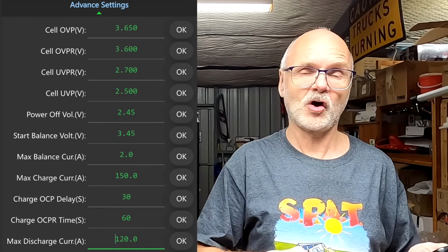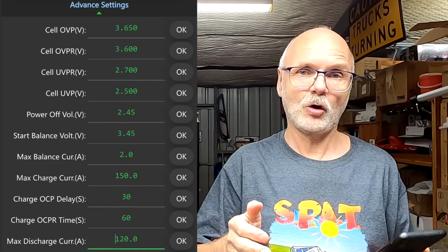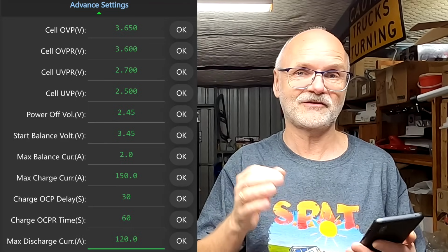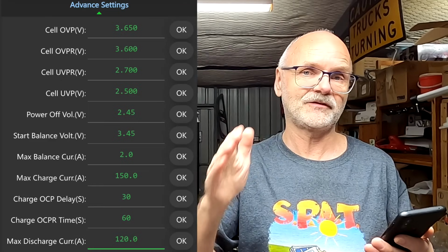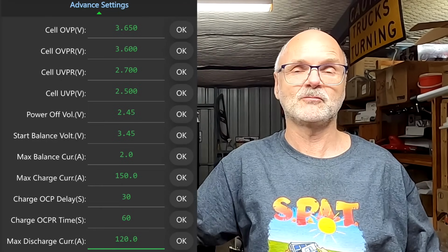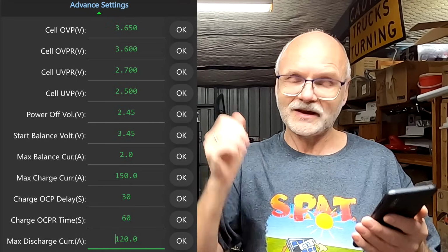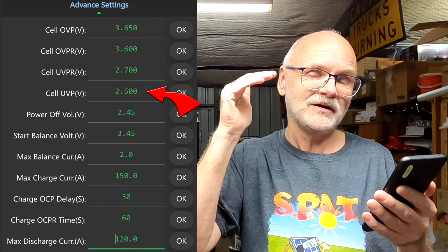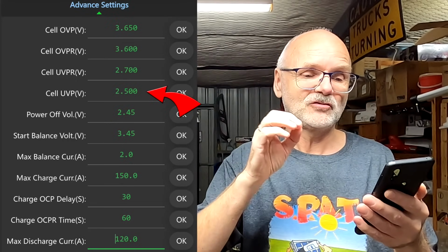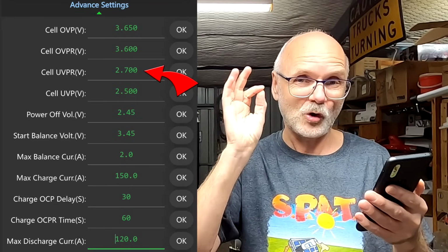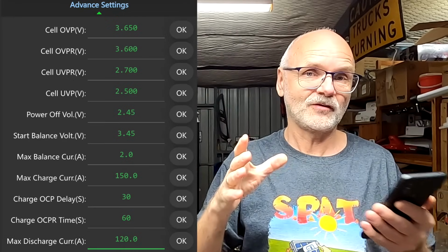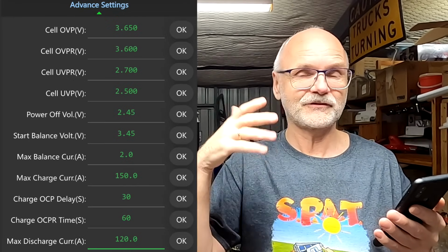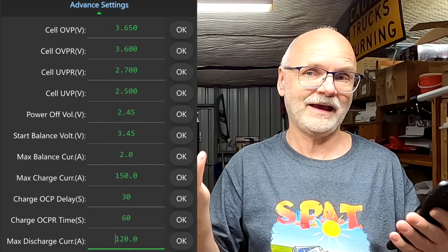If you're not at home, and if your inverter or your load does not shut off automatically at a certain voltage, the BMS will watch this, and if one of the cells hits 2.5, it says, no, there's something wrong, shut it down. And then it waits until the battery voltage slowly climbs to 2.7 volts, so all the cells need to be over 2.7. And then it turns on the battery bank again and allows the discharge of your battery again if there's still load available.